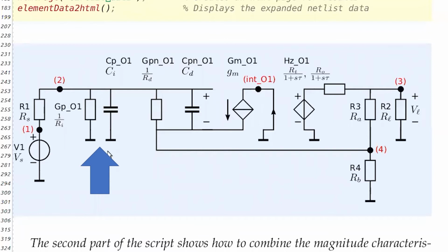This will always be a current flowing to ground if there is a non-zero input voltage. So the asymptotic gain will not be the ideal gain, which was solely set by RA and RB. So basically the controller never becomes a nuller because there's something outside this nuller.